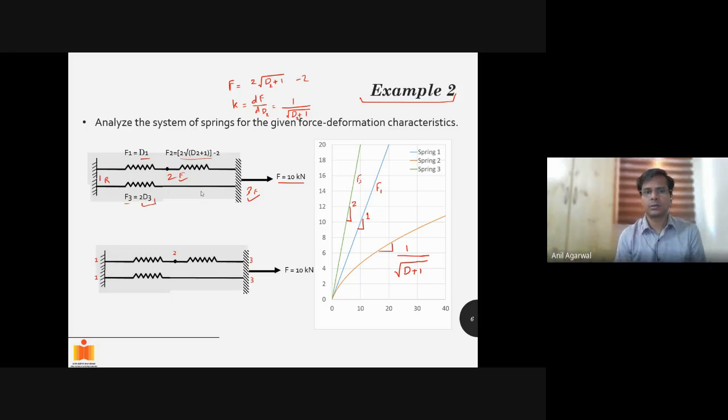So the first step will be to calculate the SFF, right? Tangent stiffness matrix. So we will start with the calculation here when the force and displacements are all 0. So SFF, for that we need to calculate S total first. For that we have to calculate the stiffness matrix of each spring first. So for the first one it is 1, minus 1, minus 1, 1. That is between first and second degree of freedom.